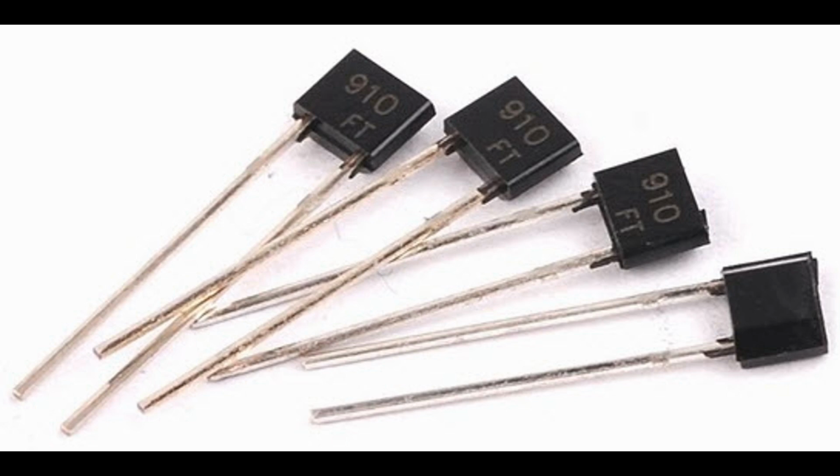This allows you to adjust the width of the frequency band that the filter affects. 5. Modulation sources. The control voltage for a VCF can come from various sources, including envelopes, LFOs, low-frequency oscillators, sequencers, and other modulation generators. This allows for dynamic and evolving changes to the filter's behavior.